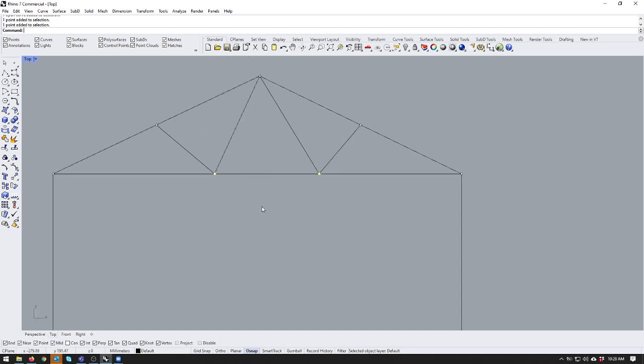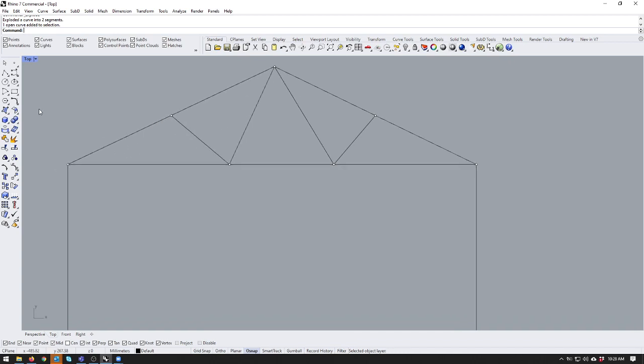So that's the type of theory that we're tapping into here: there's information associated with each of these joints, and there's information associated with each of these members for the final system to be able to calculate properly. So we're not just drawing geometry in this system now, we also need to produce a second parallel layer of information for each of these objects to describe how that object works in the system. For typical uses of BIM with Revit, that information normally helps you draw a section faster, or a plan faster, or lets someone audit or schedule doors better. You would hope. Doesn't always work that way. But that underlying information is important for the computer to be able to understand and help with that system. And so we've got to do that when we make these models.